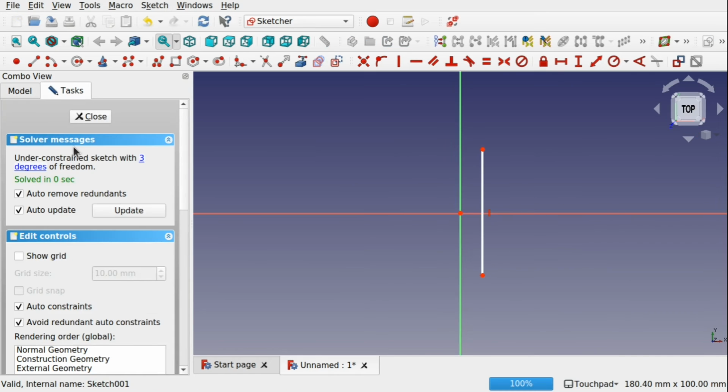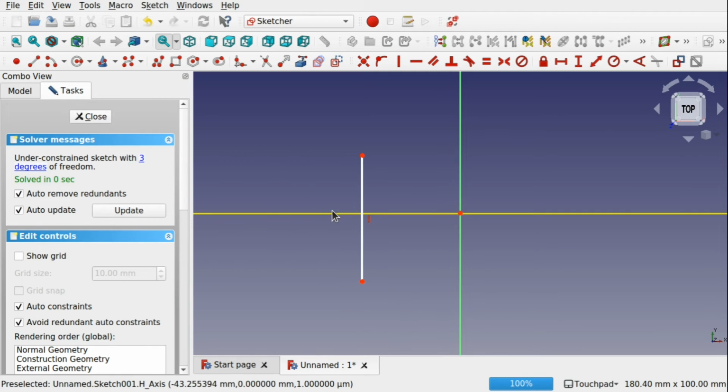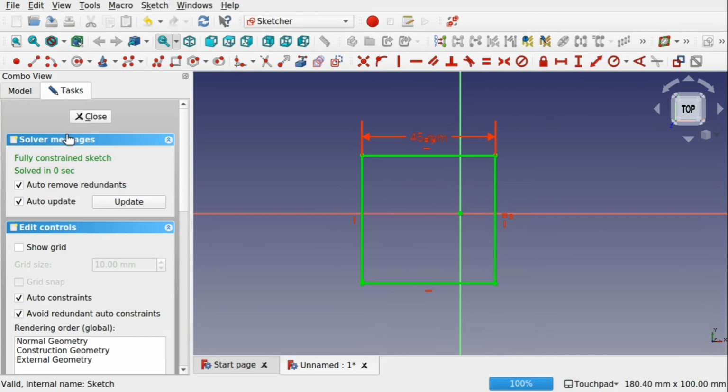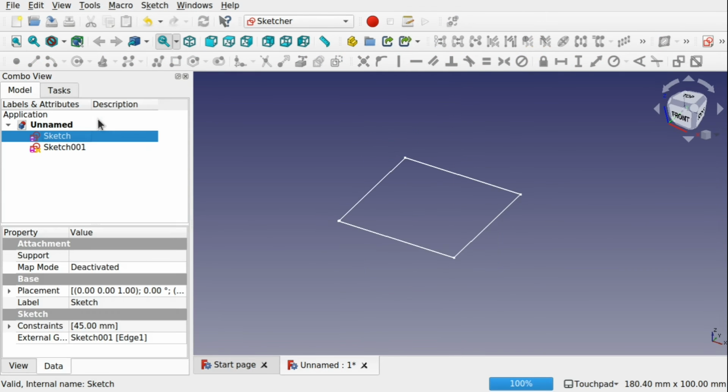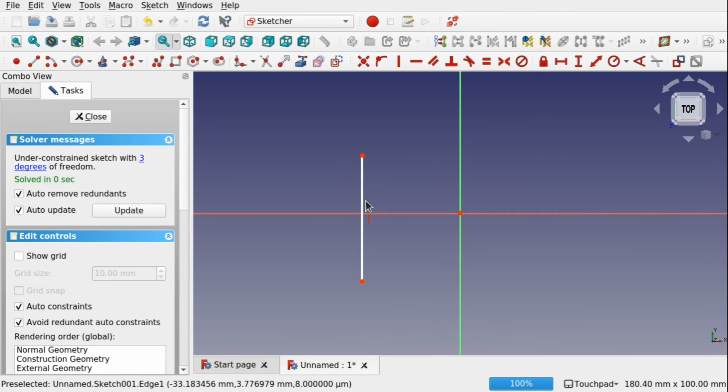It's because this sketch here is mobile, and this can cause problems because you could have constraints linking onto these sketches, and just by nudging one of them, so the one that isn't constrained, could cause your whole geometry to collapse and your models to break. So just be wary of that. So that will highlight in purple.